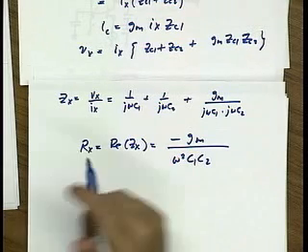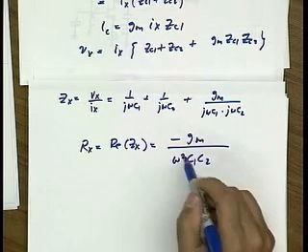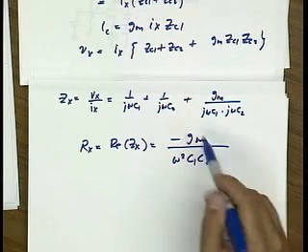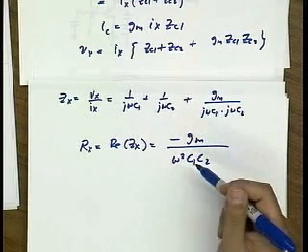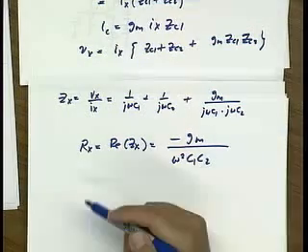It's interesting to see that there's a frequency dependence in this negative resistance. In other words, as we go to higher and higher frequencies, we get less and less negative resistance. And so this naturally tells us that this oscillator has some frequency limitation. You can't arbitrarily create a negative resistance.